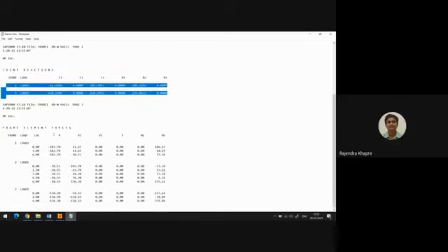And here, this is the most important part. Here there are three frame sections: frame section 1, frame section 2, and frame section 3. This column, M3, denotes the bending moment. Okay, so on frame section 1, the first vertical member, you will have 106 at the bottom and 57 at the top.